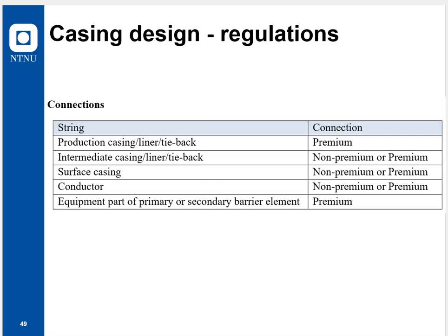And typically, the people working on the well site or on the platform offshore, they would read off the manometer either once per day in wells with problems, maybe once per week in wells with a small history of small pressure increase, typically coming from gas migration, and in most new wells, where it has been established that that pressure is not increasing, it would be once per week or whatever it would be, company philosophy.